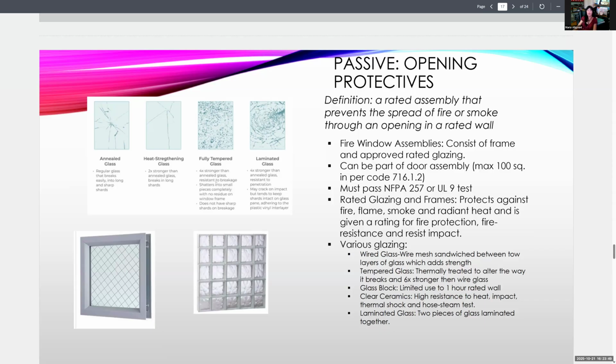And it is the type, have you guys ever broken a windshield? When the glass turns into little pebbles, like little pieces of glass, but it stays in there, it doesn't shatter in shards. It breaks like little teeny balls inside. That's tempered glass. Okay, once again, 6 times stronger than this wire glass. So tempered glass would be a great type of glass. We have that in our cars, on our windshields, so that if a rock hits, they don't break the same way. We don't want shards. Tempered glass in your shower if you fell.